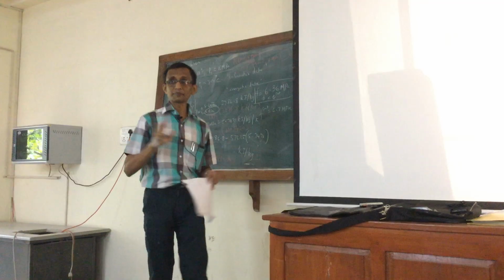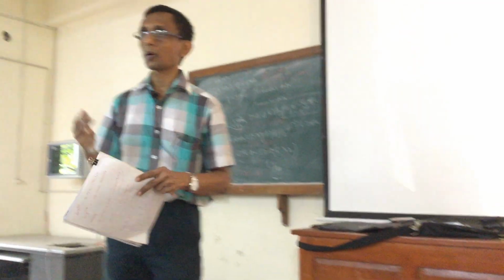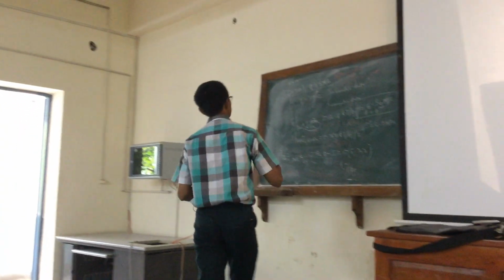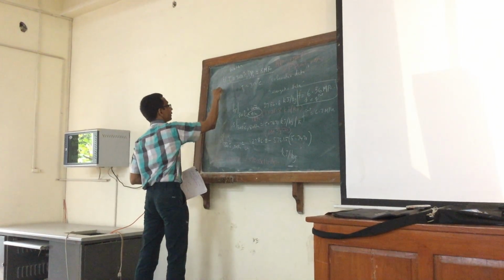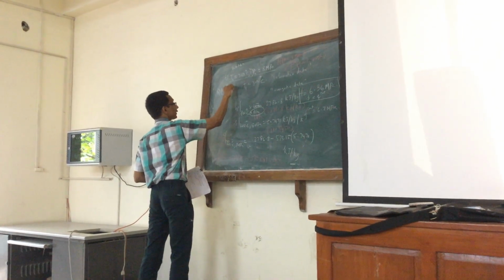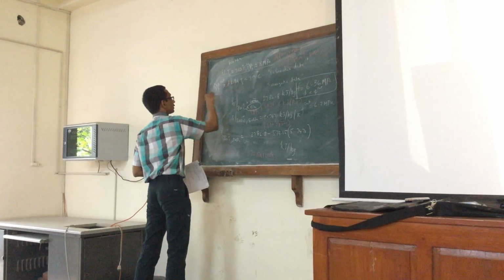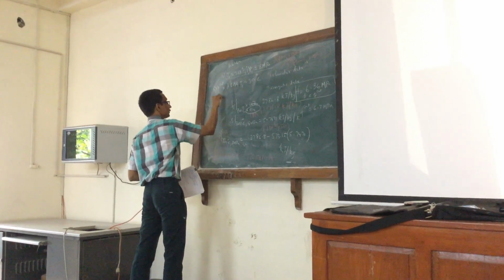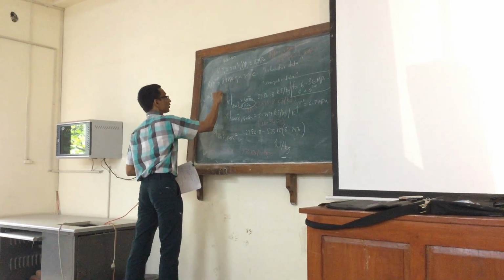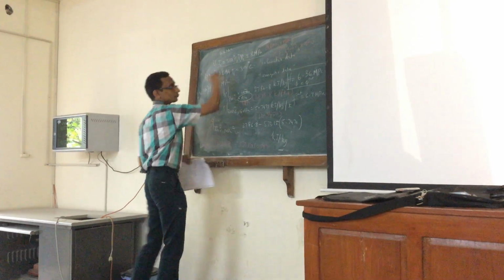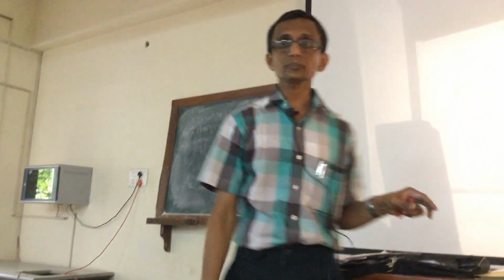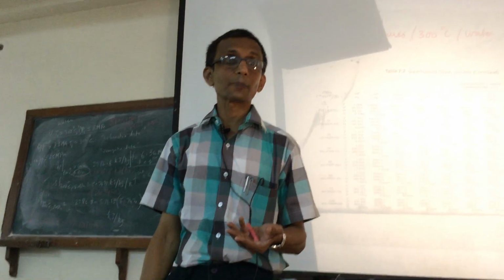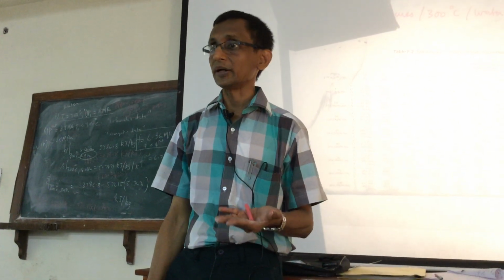Now we don't have time for the third part of the problem. Sandler says the second is saturated, P sat, all at 300 degrees centigrade, 8.6 roughly. The third one is P equal to 25 megapascal. To what state does that correspond? 25 megapascal. Liquid, right?